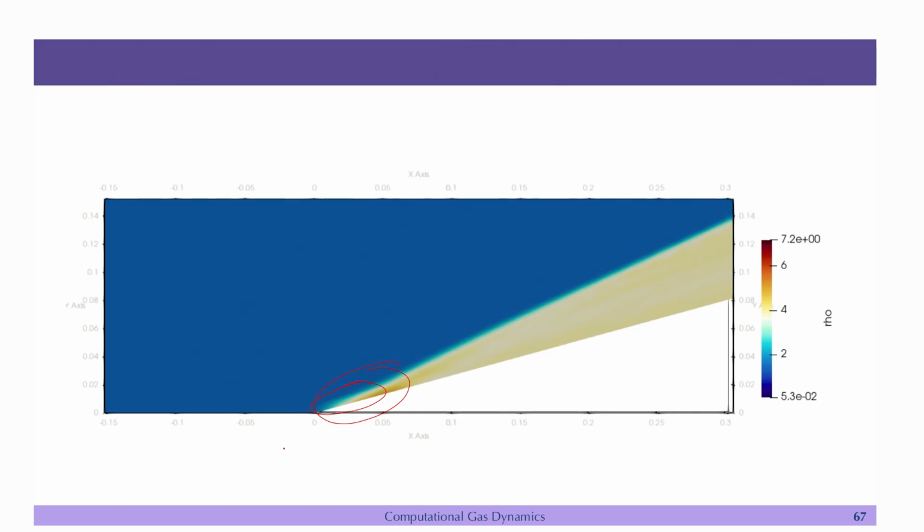Here it is not very clear, and you can see that this is going upstream. This is happening because we have chosen the laminar solver. If you take mu equal to 0, then you will get a clear solution which will basically be just a shock. But in this region you have this shock boundary layer interaction. So this is one example.